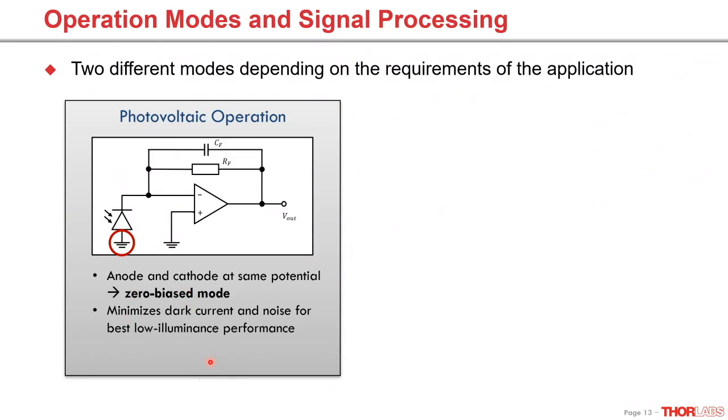In that mode, in combination with a low load resistance, like given by the transimpedance amplifier shown here, a linear operation with very low noise and very low dark current is possible over several decades of photocurrent. The limit here is some 0.5 milliamps up to 8 milliamps of photocurrent, strongly depending on the photodiode. This mode is usually taken for power measurements.